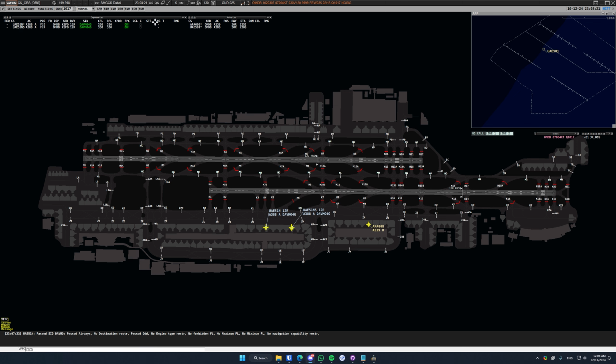This is where you're going to see the status of the aircraft. The HS is the old short field, but this is currently being discontinued, so we will not be discussing this one. The T stands for communications type. If it is blank, that means the aircraft is able to receive and transmit on the frequency. If it's /R, it means the aircraft is able to receive on the frequency, but will only reply via text. And if it's just /T, that means the pilot is a text pilot.